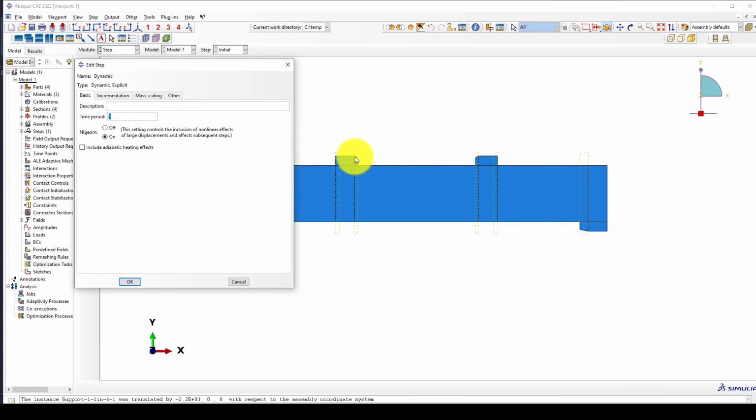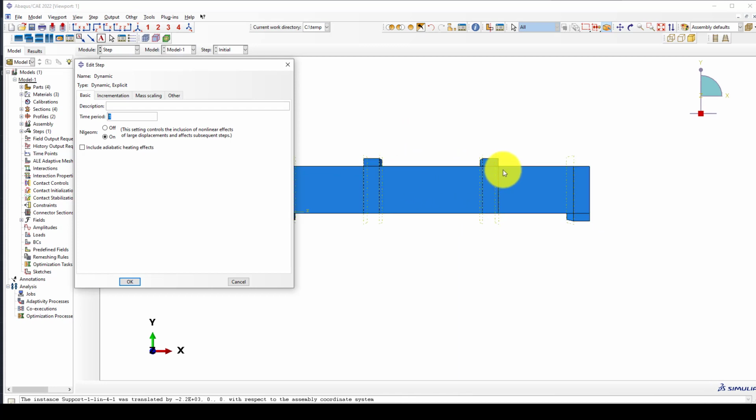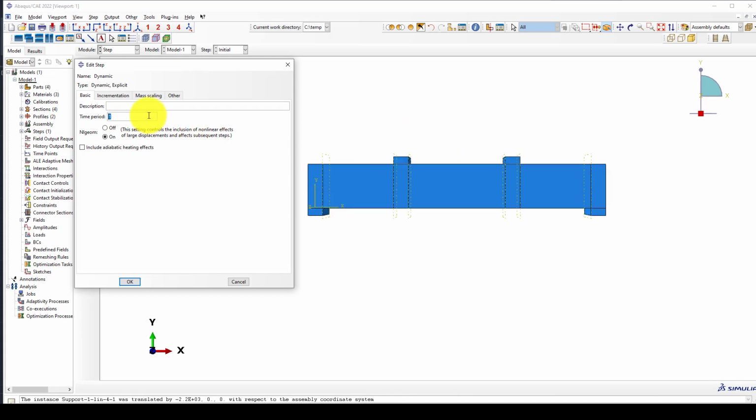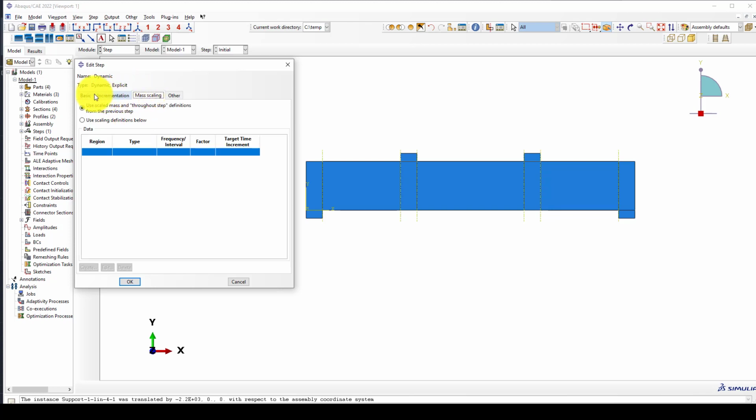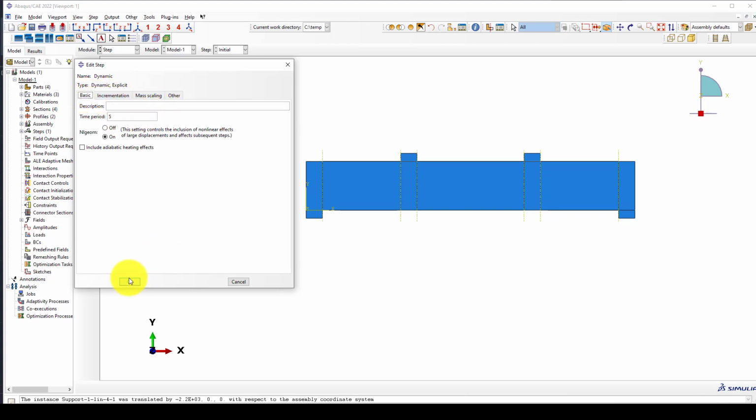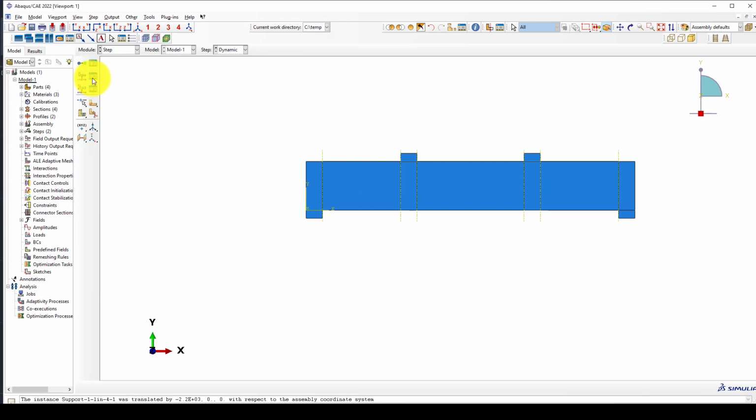The dynamic should look like semi-static by giving a large amount of time, at least 5 seconds. In case, you can also use mass scaling, but I want to ignore this.